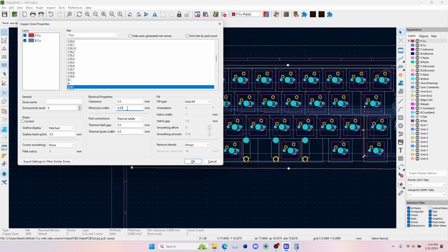Clearances of 1/4 millimeter and 1/2 millimeter. Those are pretty good. I mean, they're standard and they're pretty good. So the fill can be hashed. It can be solid. We can round the corners if we had the fill within the PCB itself, not just around the whole thing. It looked pretty cool. So let's do a hash pattern. Let's do it on, I don't know, give us a crazy angle, 20 degrees.